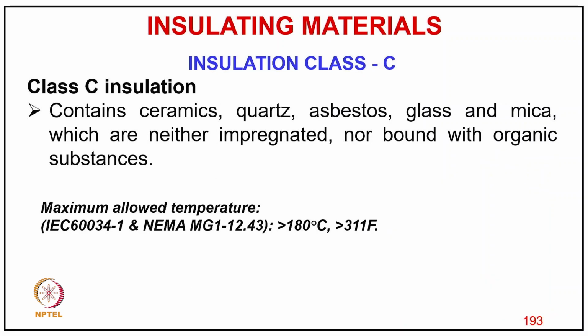photograph. Now coming to class C insulation, it contains ceramic, quartz, asbestos, glass and mica, which are neither impregnated nor bonded with organic substance, and maximum withstand temperature capability is 180 degrees Celsius or 311 Fahrenheit.